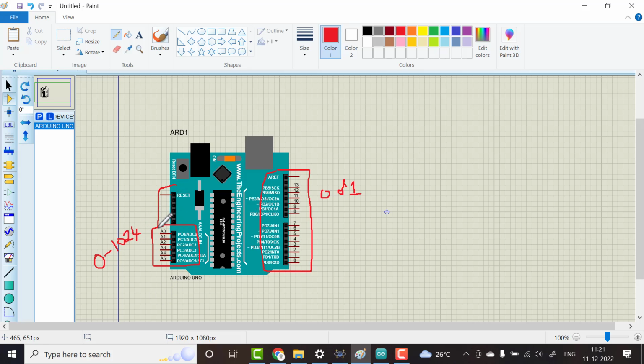So there is a power supply section. Here you have grounds, 3 volt, 5 volt, and other power supply related pins. And this is a pin where you connect your Arduino hardware to your desktop or laptop or any system using a cable. And this section is to connect a 12 volt power supply. So if you want your Arduino to run independently without connecting a system, after your complete project, you can connect a 12 volt supply to this section. And here you have a reset button.